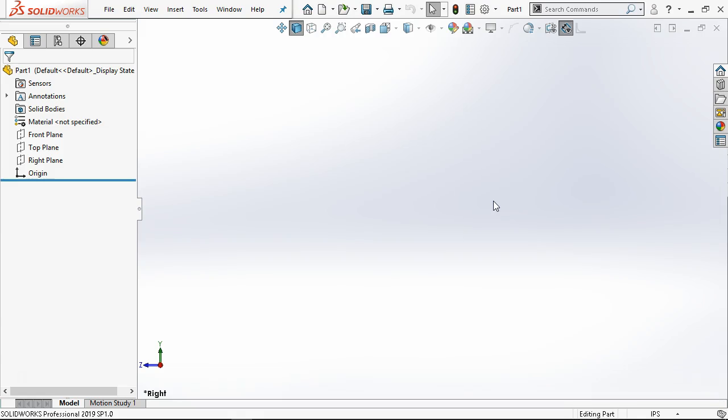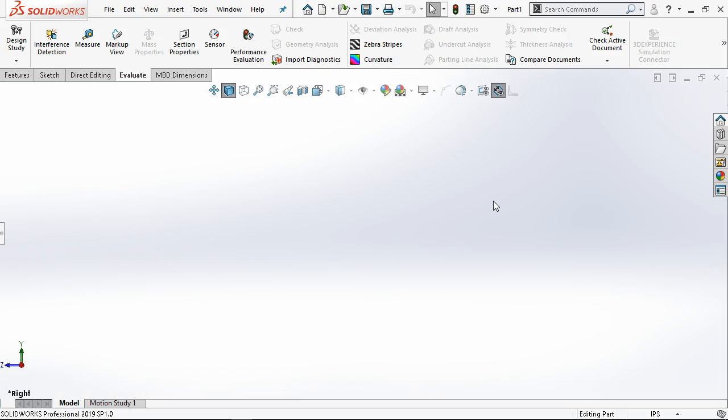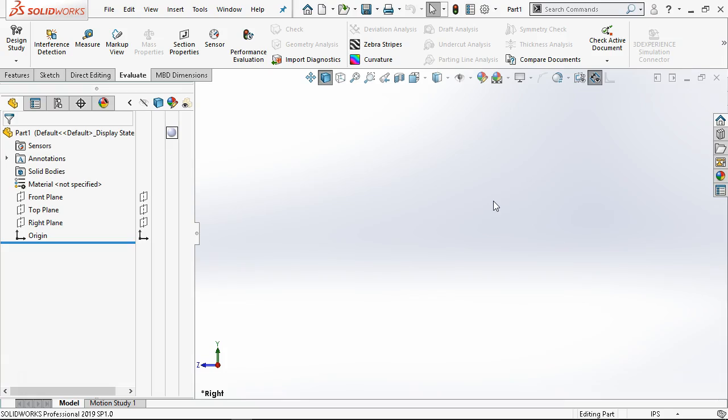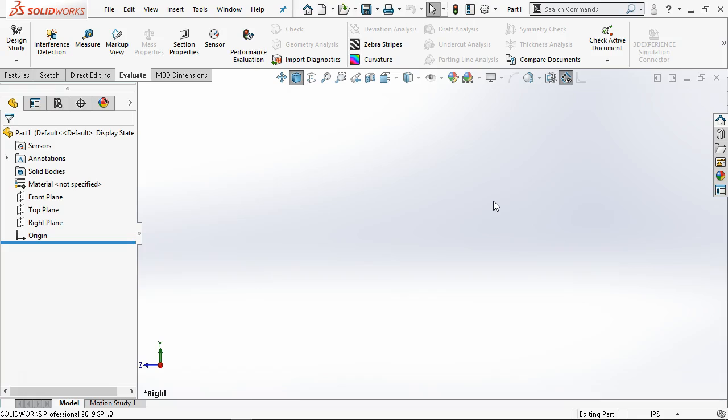F10 gets rid of the command manager, makes it a little bit more of the screen. F8, that one condenses a little bit more. F9 is the display will extend and contract. Right, so there's a lot of those keyboard shortcuts that if you hit something accidentally it may change and you won't recognize it until the next time you go to use it, and then where's it at?